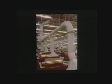A duct should be of the proper diameter and constructed of appropriate material. For example, when ventilated air contains sulfuric acid, stainless steel duct is often used. Be sure to maintain an adequate transport velocity in the duct, or the duct may fill up with dust. An alternative is to provide clean-out openings at intervals throughout the ductwork. This, of course, increases maintenance requirements.